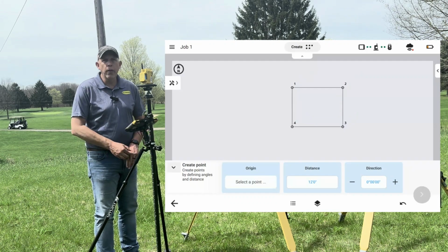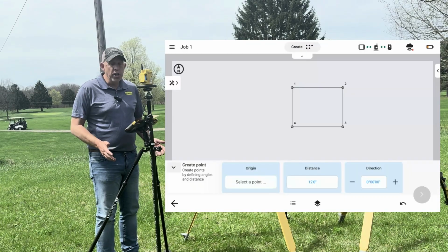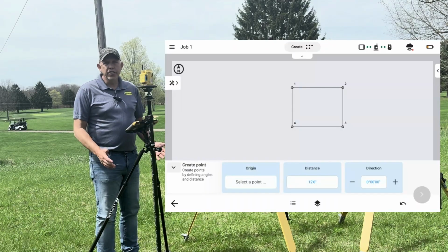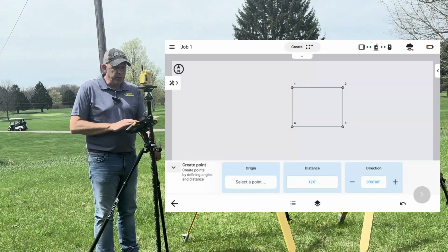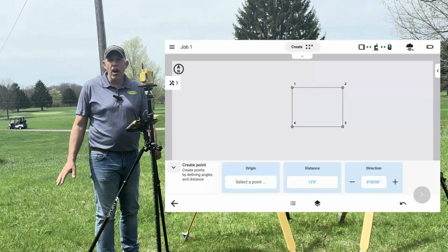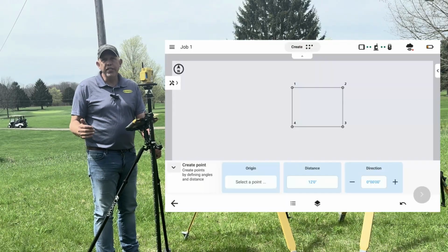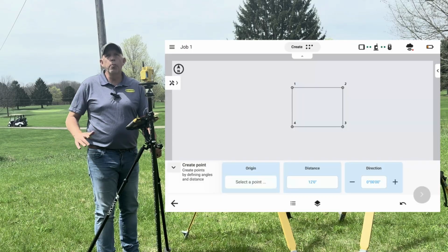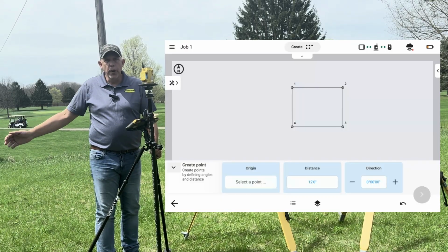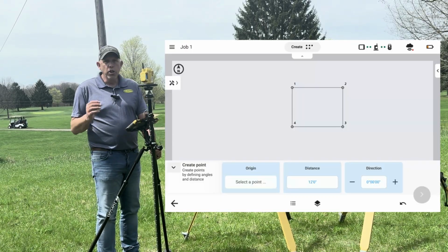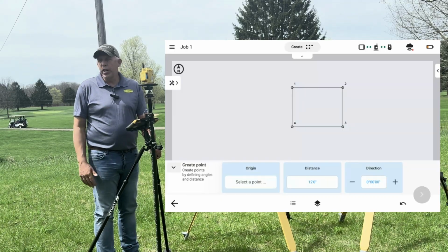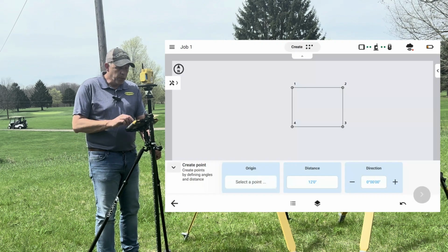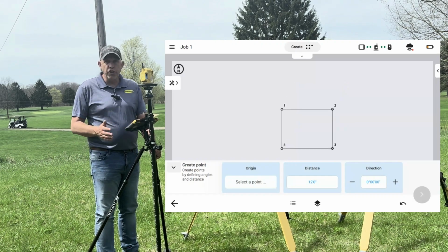You're just walking around and drawing the job in. When you're on site, you need to know what you're going to have for control. You always got to start with 2 points. If we were just making this box fit on the ground, we could put 2 stakes in at 15 foot 6 apart and use those as our 2 control points, and then it would know where the rest of the project is. We're just going to pretend that we came out on site, we field verified that it was 2 10-foot offsets. And we're going to say they were off of point 1 and 2.